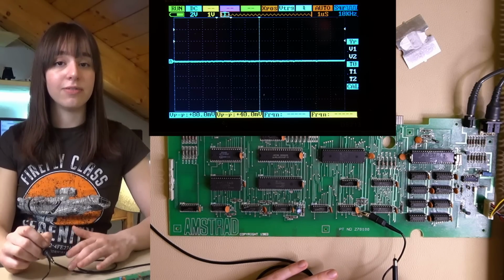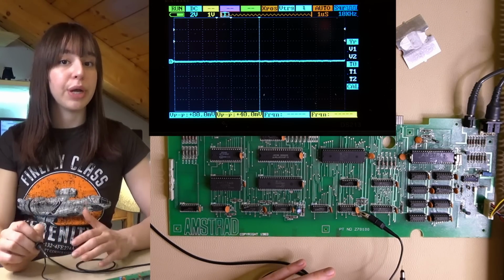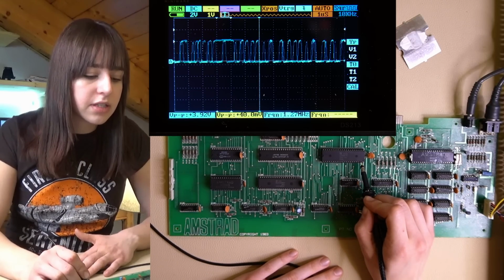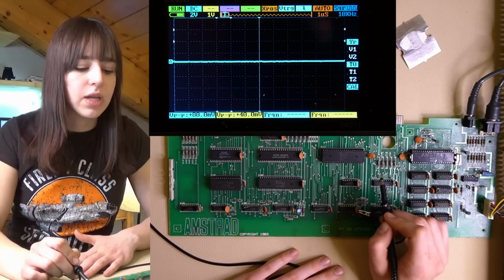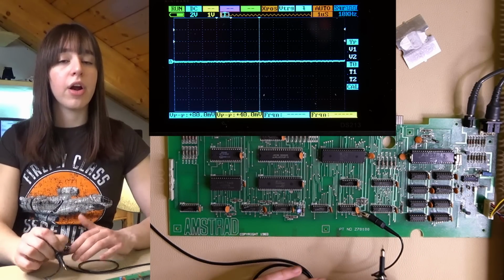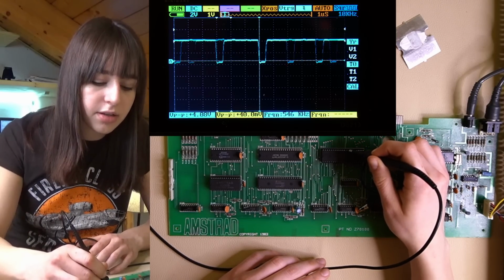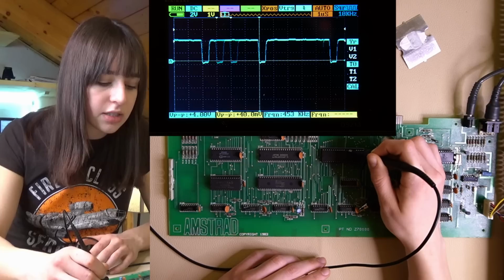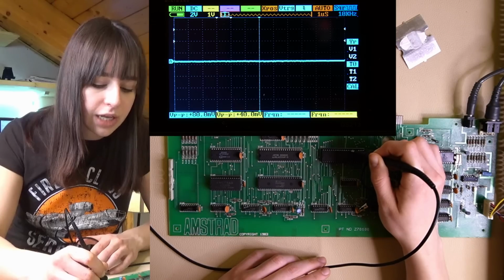At this point I'll focus on the Z80. A useful signal to check is the memory request at pin 19, and it's around 1.4 MHz. So I can assume that's not the problem. Other two useful signals to check are M1 and refresh at pin 28, but that seems correct, as it's around 333 kHz, and 27.